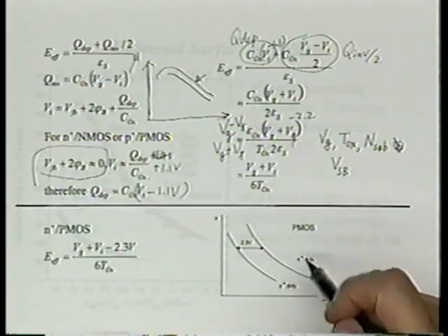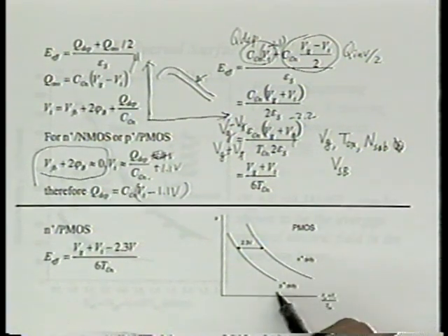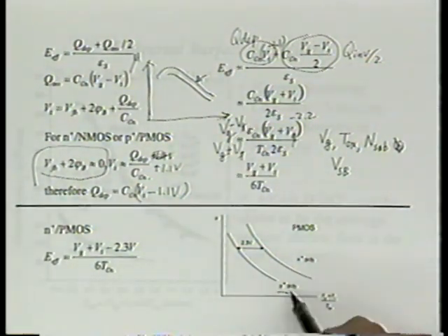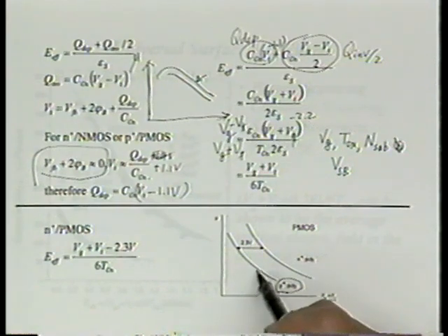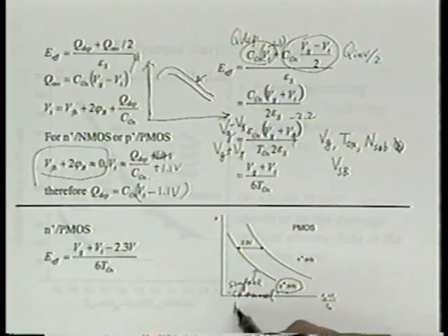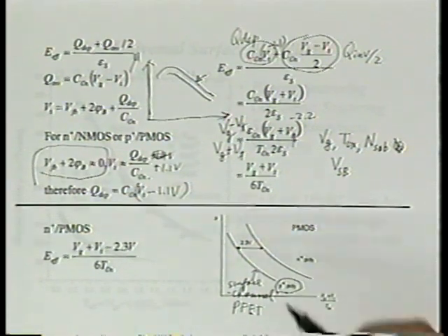You see, this is known, by the way, you have heard this term. I think I briefly introduced the terms surface channel and buried channel when I introduced P plus poly PMOS and N plus poly PMOS. Did I use that? Did I not? I didn't? I'm sorry, maybe not. Okay, let me tell you. P plus poly is known as a surface channel PMOSFET, PFET. Okay?